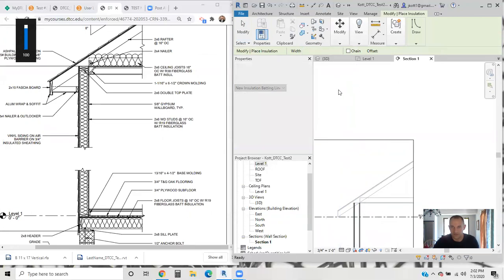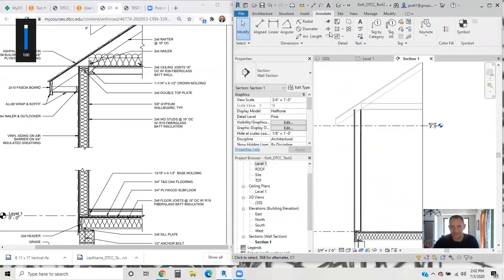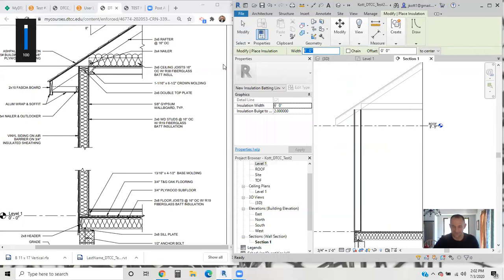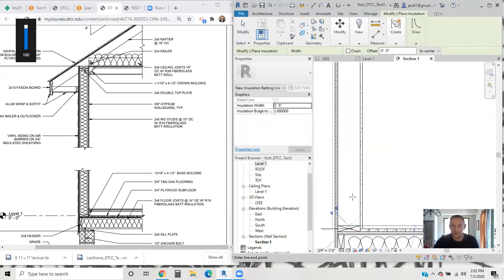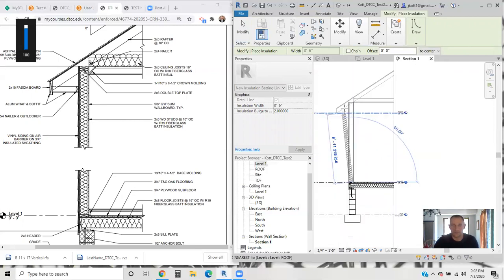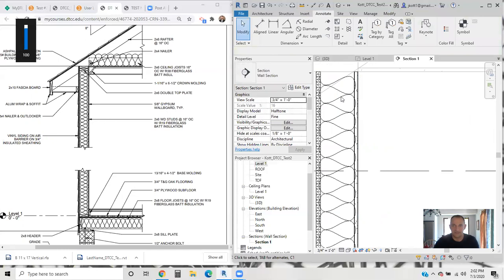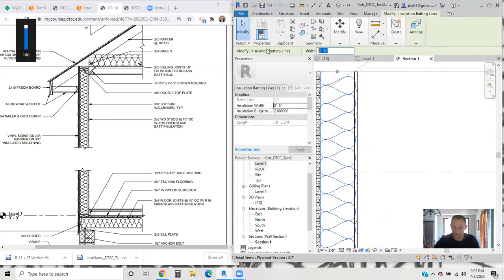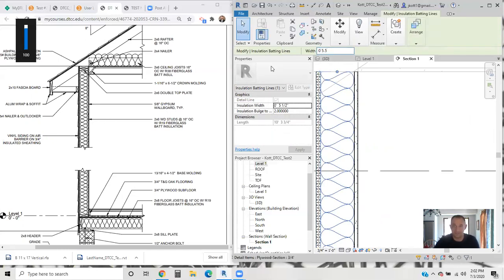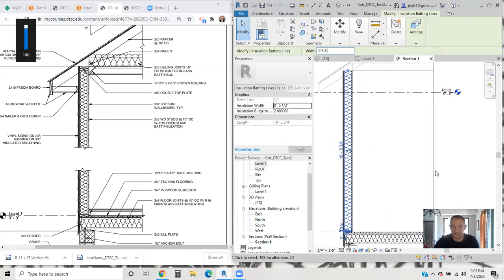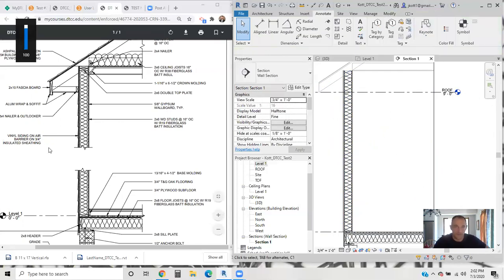So now I set the width of that to 6. It came in way too large, so we have to set it to 6 inches, not 6 feet. We draw this up and up the wall assembly just like this, and looks like I was right the first time. It's actually 5.5 inches and not 6 inches. I'm going to leave the floor as it is for now.